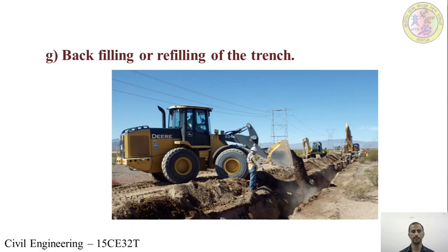So these are the steps for laying the pipes. Starting from studying the detailed map and laying the pipes with respect to the ground, digging the trenches, preparing the bottom of the trench, laying the pipes, joining them, and at last backfilling the trench.